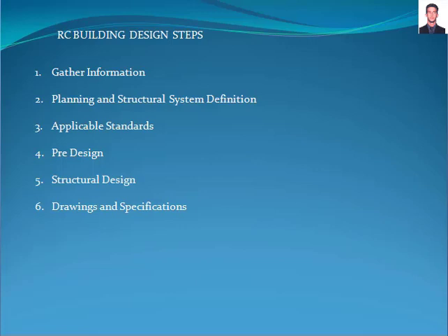Reinforced concrete buildings have 6 basic steps, which are: gather the basic information, the planning and structural system definition, applicable standards, the pre-design, which is the part that we are going to talk about in this tutorial, the structural design, and finally the drawing and specifications.